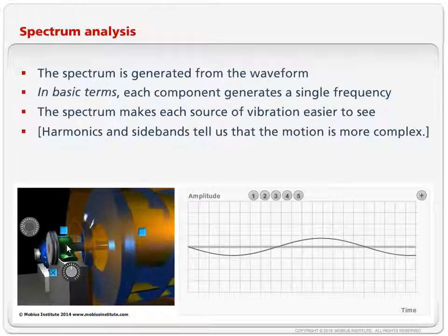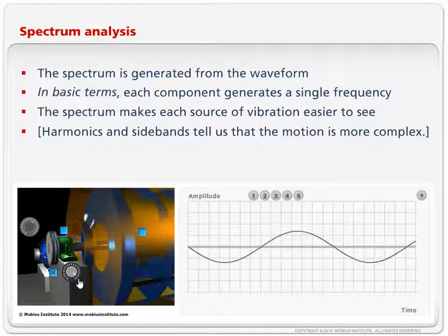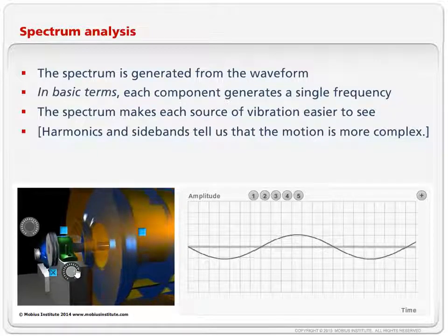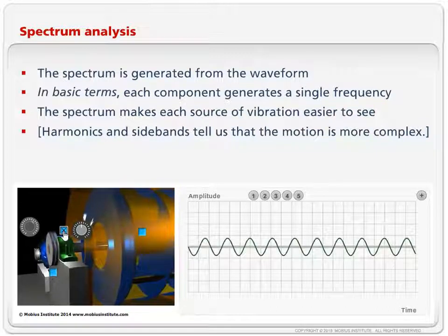So there is the vibration at the running speed, at the once per revolution frequency. If I speed up the machine, then like we saw just before, the waves get a bit closer together. If I have more amplitude, I get a bigger signal. So from this grey shaft, I've got this grey vibration. That's sort of what we saw a moment ago. I'm going to turn that off, and let's have a look at the green bearing now.